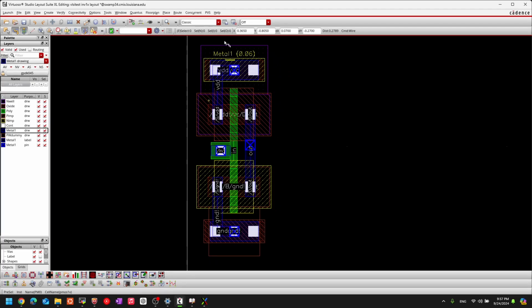So don't be afraid of going through the DRC check. So let's do a DRC check. Normally, this is a really simple circuit to build, a layout, but in more complex circuits, what layout engineers would presumably do is do DRC checks from time to time, just so as the complexity grows larger in these circuits, they could avoid a bigger list of DRC violations. They would go step by step, do a DRC check on every action they did inside the layout